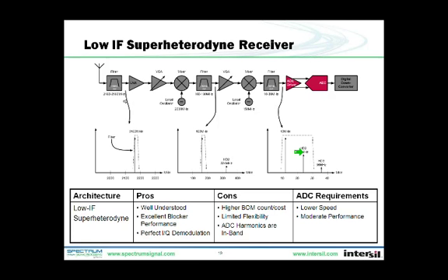So our channel at the antenna is 2.16 to 2.18 gigahertz, and this is selected using a bandpass filter. This is followed by a low noise amplifier and then mixed with an LO at 2 gigahertz to provide our IF from 160 to 180 megahertz. This is then bandpass filtered again and followed with another variable amplifier and mixed down with 150 megahertz to give us our output spectrum of 10 to 30 megahertz.